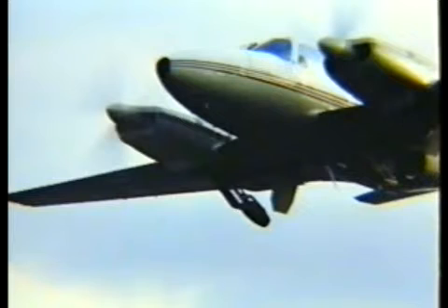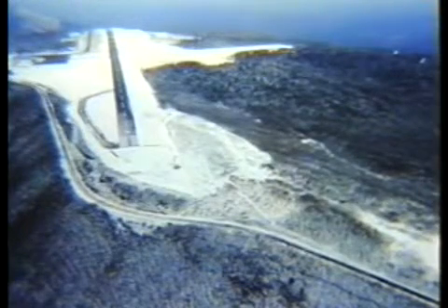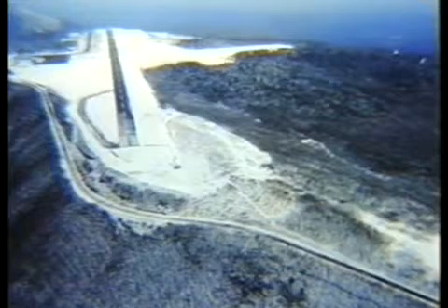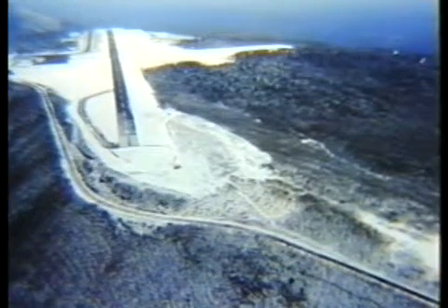Now, before we talk about the how-tos of going around, we have a suggestion. Experienced pilots always decide in advance on a go-around point on the runway. If they haven't touched down when they get to that point, they simply take it around and do it all over again. You may want to adopt this policy for yourself as well. And remember, at a high-density altitude airport, or one where there's rising terrain, you might actually put your go-around point somewhere before you get to the runway.